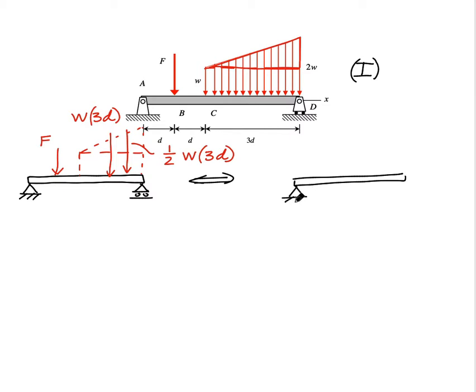So the third system is going to be a simply supported beam with an equivalent load there of R at some distance there of D. Our goal there is to find both D and R. So again, this is 2 and this is 3. We've already made system 1 equivalent to 2 by replacing that line load by its two parts there of 3WD and 1/2 of 3WD.